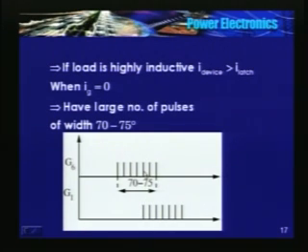At that instant G6 still has a few pulses, because even if the current has become 0 somewhere, at this instant G1 is getting a trigger pulse, and there is a trigger pulse for 6 also. So current you can establish in the circuit. Okay. So far so good.